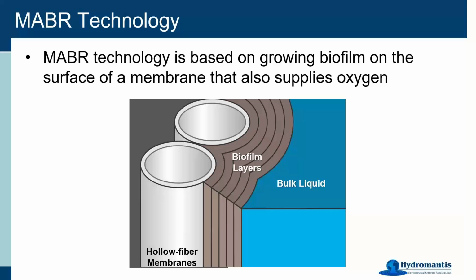It is the mixed liquor in your particular system. So that biofilm is there to take up those nutrients, take up that COD. There can be biomass out in this liquid as well, and you'll see later that, of course, there's attachment and detachment to that biofilm system as well. So you have this system of a fixed media, some biofilm that's growing there, and your bulk liquid.